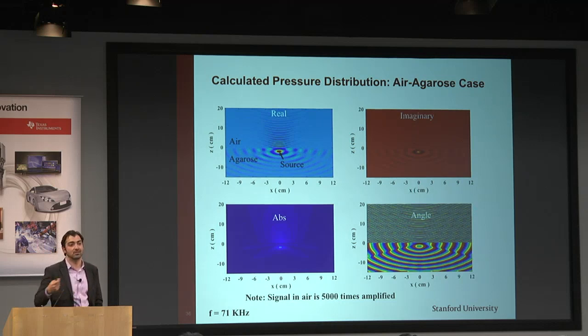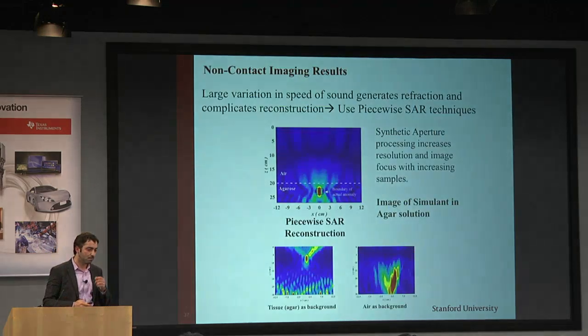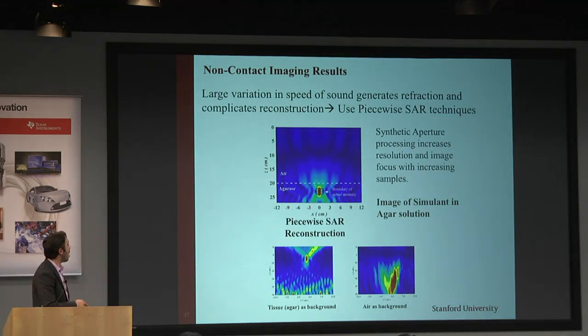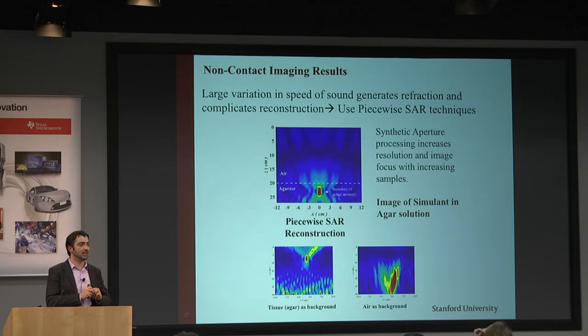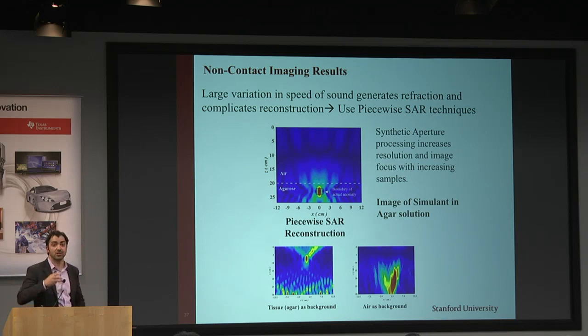So I'll give you an example. This is our optimal reconstruction technique, where we do a layered SAR technique. And we're now moving to techniques that use the Green's function for the problem and apply it to get a more focused response and more corrections for the edge refractions from multiple layers. But if you don't, you actually see the target in a different location, and you completely lose your signal to noise ratio and resolution. Right? So that's a problem with just the speed of sound and refraction.